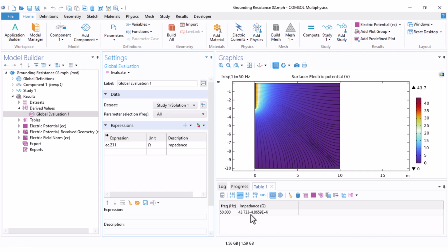As you notice, the imaginary part is negative. It should be so because we know that in a phasor system, in a continuous sinusoidal situation, the voltage of a capacitor should follow the current by 90 degrees, and this is minus j or minus i in a complex system.